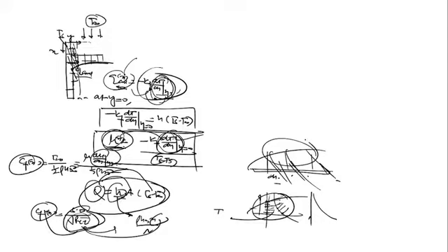Same thing in the mass transfer. There is a role of mass transfer coefficient. Mass transfer coefficient comes into picture because there are too many complex mass transfer applications where the flow is not well understood, and if the flow is not well understood, then we can't find the concentration profile. Once we can't find the concentration profile, then at the wall, although the mass transfer is by molecular diffusion only, we still cannot find the rate of mass transfer, because it requires the knowledge of concentration profile. Once the concentration distribution is known, only then can you differentiate dC/dy at y equal to 0, and find the rate of mass transfer. But we must know the concentration profile, and that we are not able to calculate at all conditions.